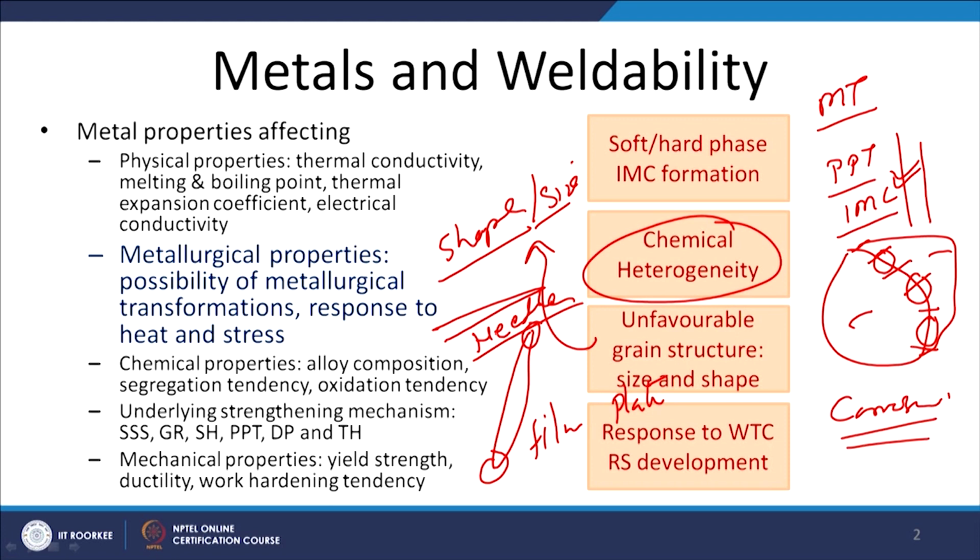And the increased concentration being offered by the intermetallic compounds and phases at the particle matrix interface will be promoting the formation of voids and easy crack nucleation.